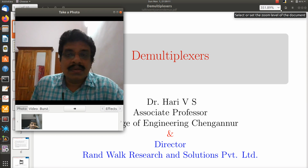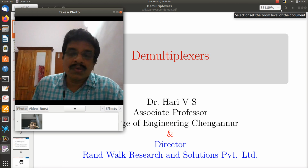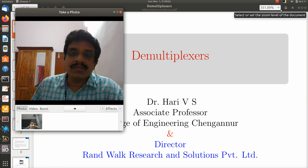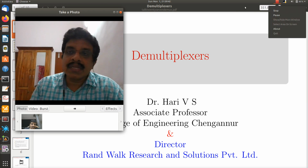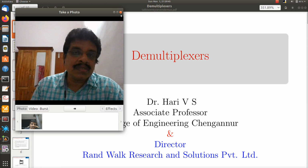So today we see the reverse operation, that is the operation of a demultiplexer. What the demultiplexer does is there is a single data coming in, maybe it's a multiplexed data coming in, and this data are placed on 2 raised to n output lines. So one single data line is coming in, and this data are placed on 2 raised to n output data lines. So this is based on the select lines. This placement is based on the select lines. So let me start with that presentation.